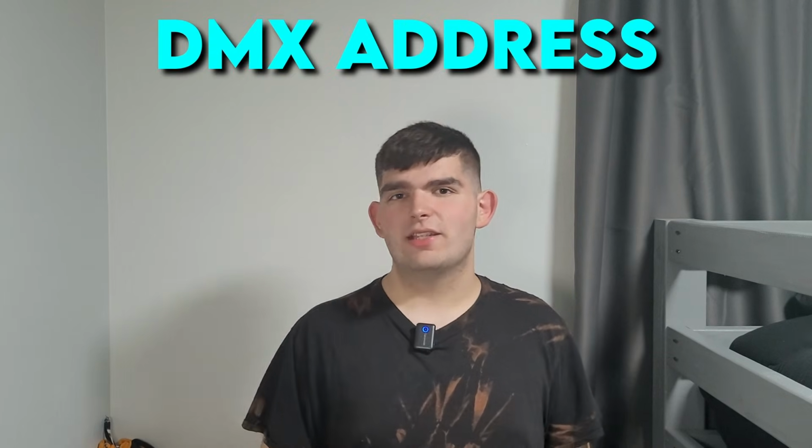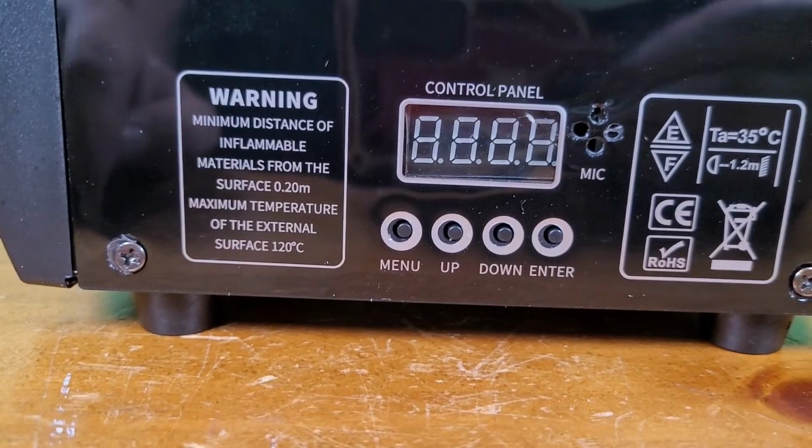And this is why we need something called a DMX address for each device. A device's DMX address is used to tell itself this is the channel you need to start reading data from. Most devices normally have built-in screens or menus so you can go through and set the start address yourself. However, there are a few occasions where some rare devices may not allow this, and they'll be set to use specific channels. We don't have to worry about that though right now. But let's do a quick example right now to see how this DMX start address works.